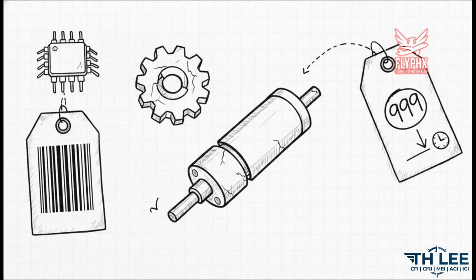A parts manufacturer approval or PMA article must permanently display FAA-PMA right along with the holder's name and part number. A technical standard order or TSO article needs the specific TSO number, the designation letter, and either the serial number or date of manufacture. Now, critical parts, those are the ones with mandatory replacement times or strict inspection intervals, demand a unique serial number to track their life cycle flawlessly.